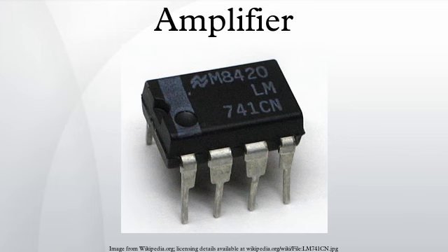The image of the conduction angle is derived from amplifying a sinusoidal signal. If the device is always on, the conducting angle is 360 degrees. If it is on for only half of each cycle, the angle is 180 degrees. The angle of flow is closely related to the amplifier power efficiency. The various classes are introduced below, followed by a more detailed discussion under their individual headings further down. In the illustrations below, a bipolar junction transistor is shown as the amplifying device, but the same attributes are found with MOSFETs or vacuum tubes.